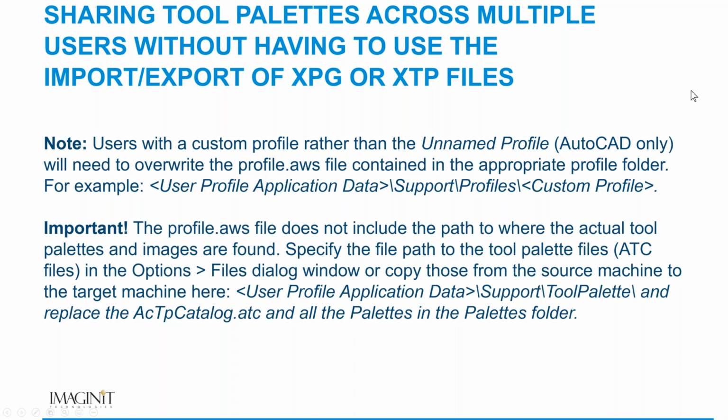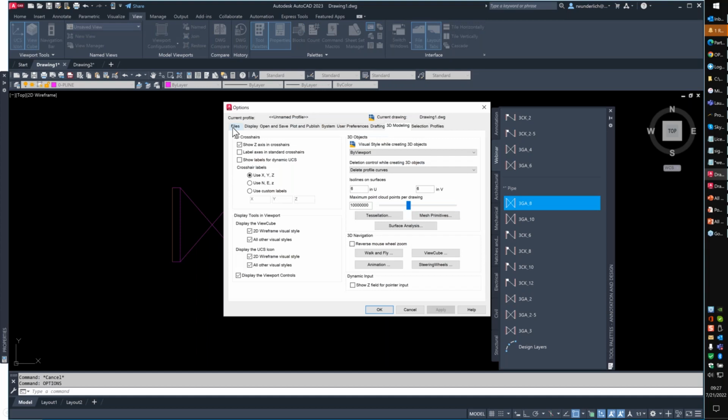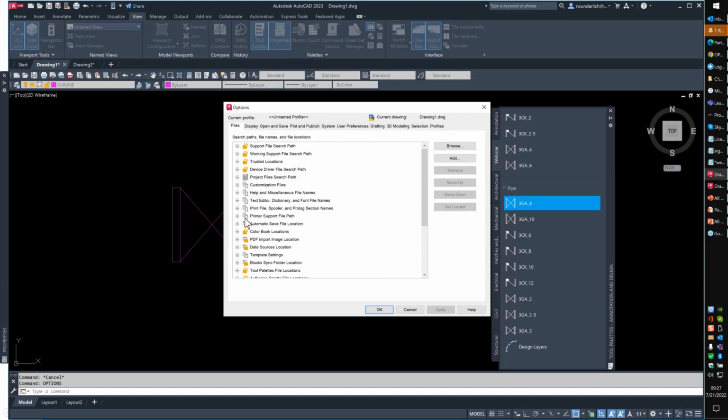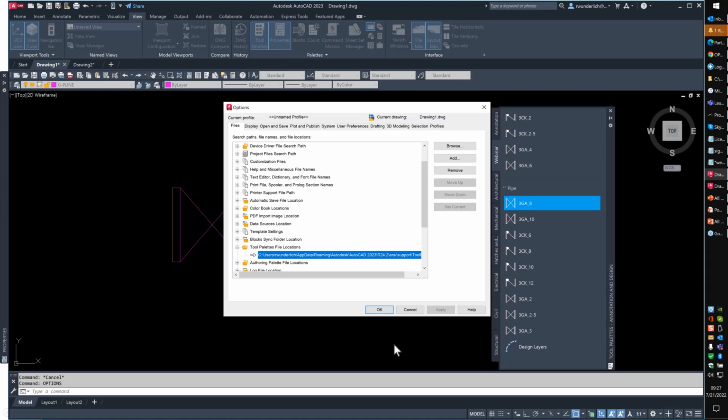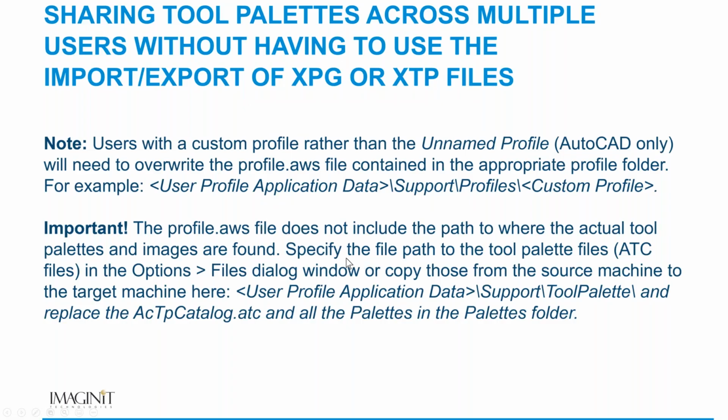So again, we come back into AutoCAD and we're going to talk about the options here. So under files, and we come down here to tool palettes. This is where I'm currently pointing. And let's see. So this is where all the tool palettes are stored. This is where you can change to a network location. And you can point everyone there. So if you want to go that route, which can be done, you'll want to make sure...